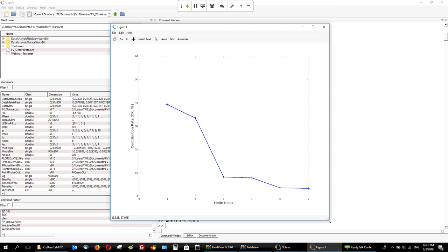All right, so what are we looking at? So again, 900 modes have been computed, but then they've been sorted by significance, and you can see the first one over here. So you can see that the line is really dropping quickly, and if we were to do the math, from mode 5 and above, really all these modes after mode 5 are contributing for less than 5% of the velocity.